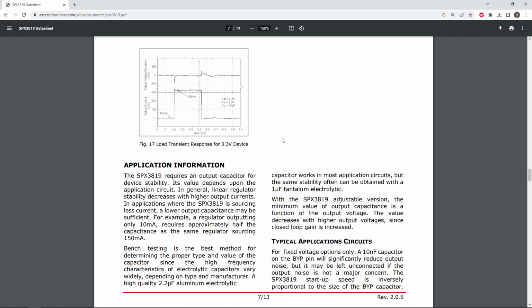If you choose the wrong types of capacitors for many older devices, and even some modern ones, the regulator can become unstable and your output voltage will fluctuate. Typically, the manufacturer will recommend a minimum value, type, and maybe an alternative value and an alternative type. The reason for oftentimes using electrolytic or tantalum is because these specific types of capacitors typically have a higher ESR, which in the case of LDO regulators aids their stability.